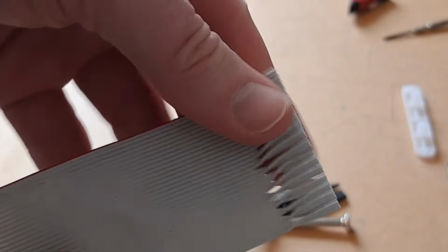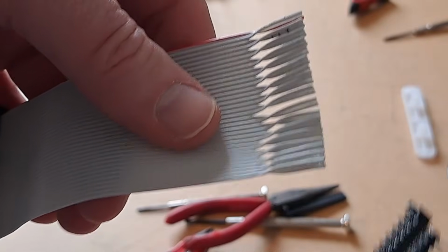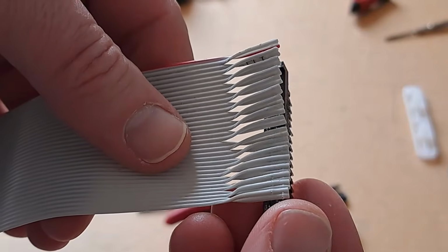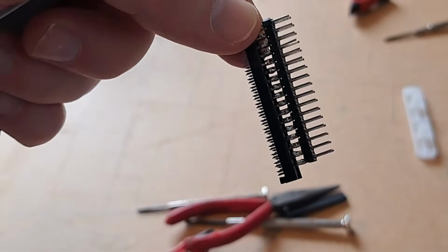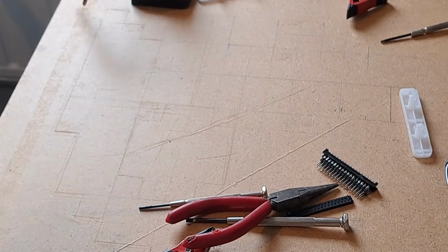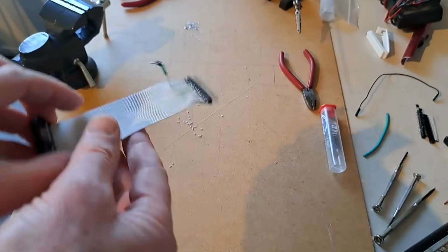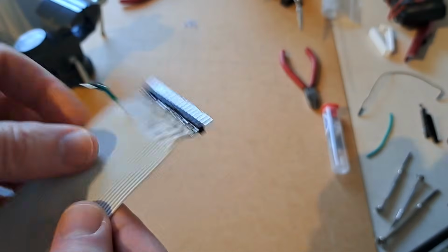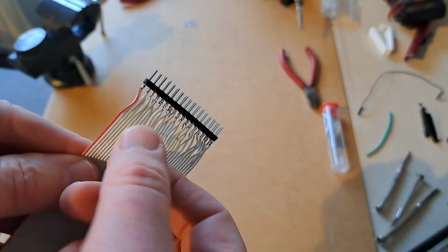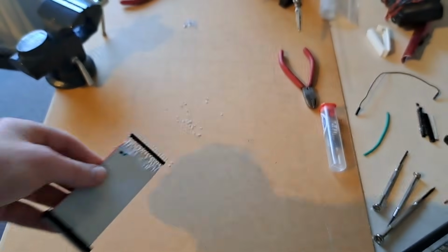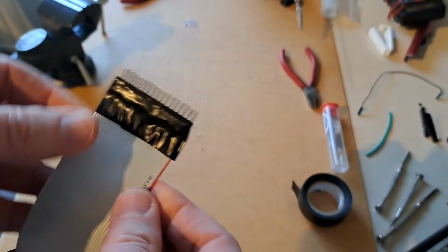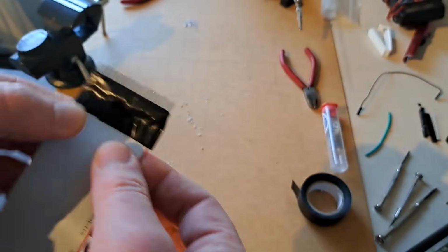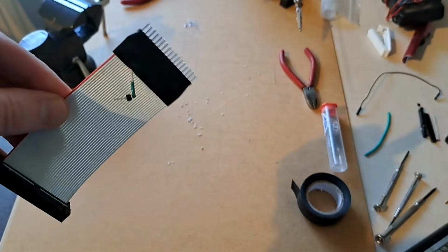I've tried recrossing the ribbon cable before it goes into the connector. But I cannot get it to fit onto this connector again now that the pin header is in its place. And a radical change is needed. I removed the pin header from the connector and soldered it directly to the wiring. And here I also disconnected pin 10 again. And I also covered this with electrical tape. It's not the prettiest solution, but as long as it works.